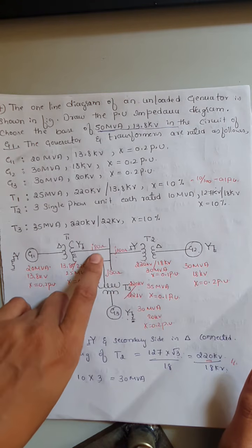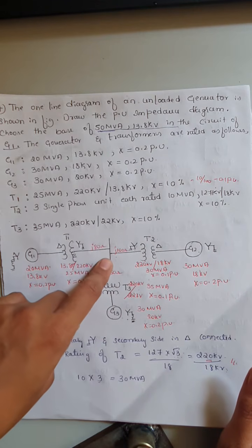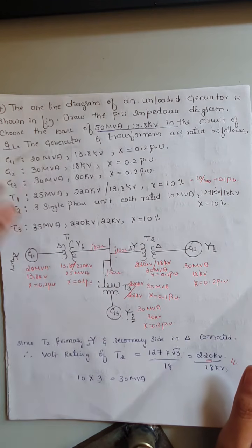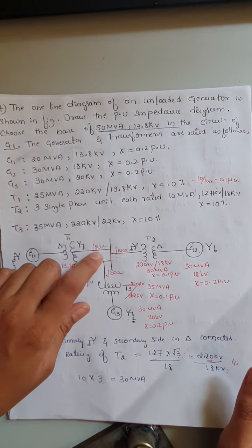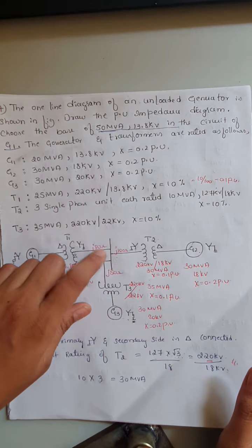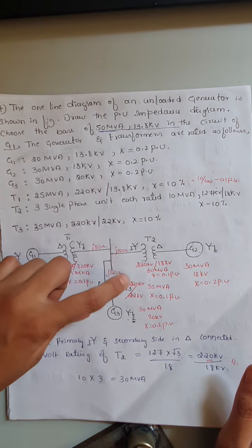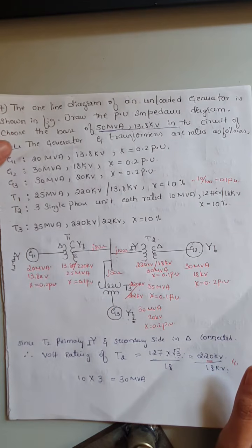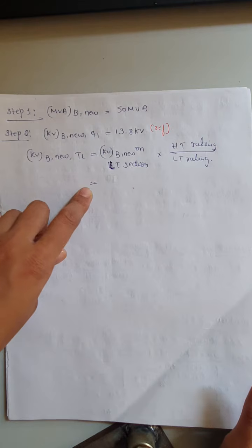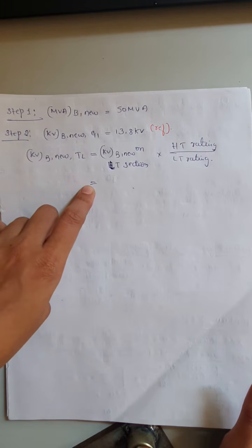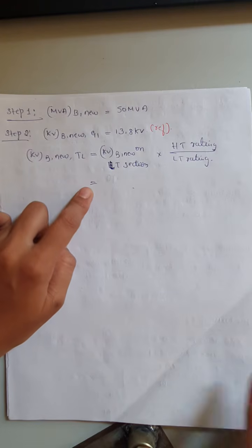Since all the transmission lines are carrying the same voltages and are connected to the same bus bar, we can go with one single base voltage calculation for the transmission line. Instead of doing it 2 or 3 times, we'll go with one single calculation only. This value will be the same for all the transmission lines, that is J80 ohm, J100 ohm and also the J50 ohm line.